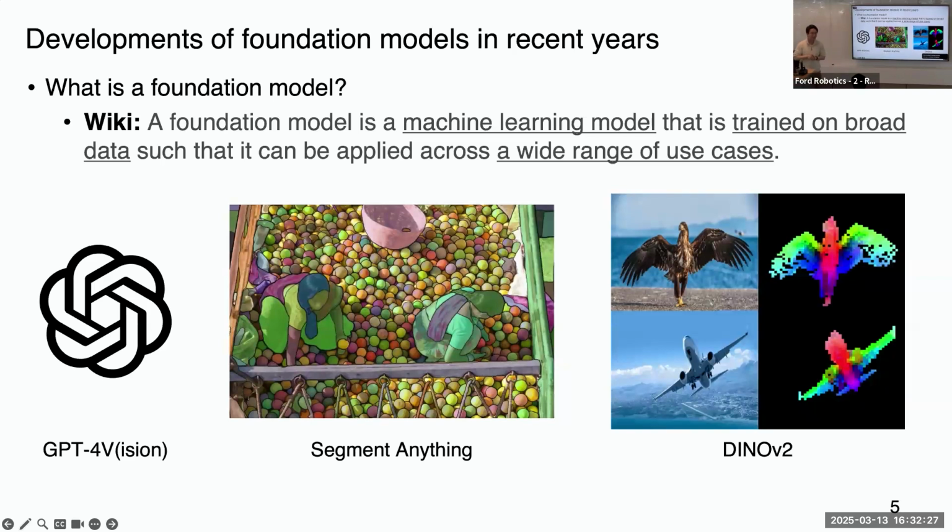How are you going to grasp based on that? At the lower level, we understand, for example, that the end effector has to get closer to some key points, or we can specify certain relationships between different key points. And if we need to grasp, we call another very good grasp planner called AnyGrasp. We use AnyGrasp to synthesize local grasps, meaning when the robot knows it's getting closer to some key points and has to perform these grasp actions, we call AnyGrasp to synthesize local grasping actions. So coarse guidance from these key points.